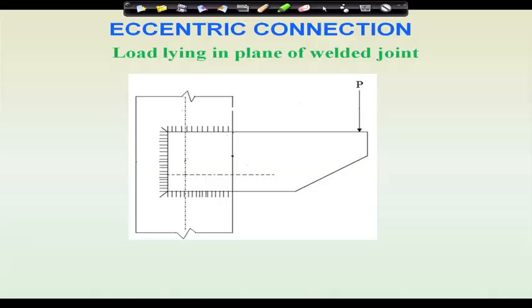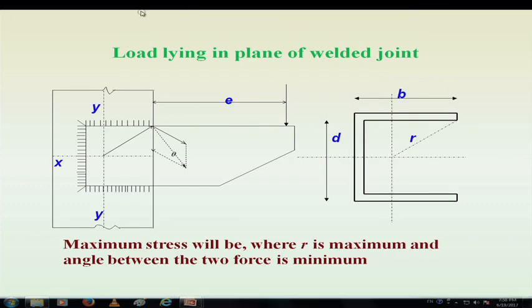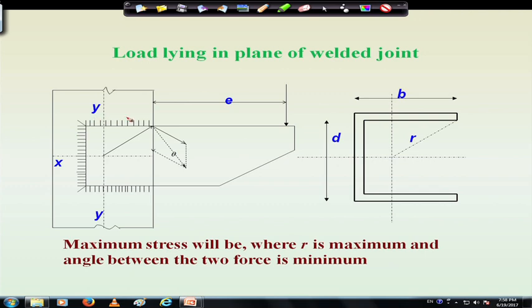So, coming to this picture, if there is a force P, then a moment will come here as P into E. Also, P as a concentric force will act here, P and P into E. Because of that, stresses will be generated on the weld.